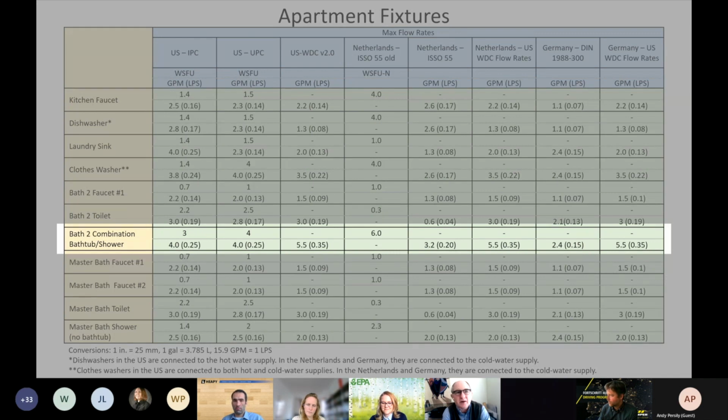So Dan, this is Gary. I've measured the flow rates coming out of combination tub shower valves, the ones that are ASSE 1016 protected for anti-scald, which is the modern tub shower valve in the US. And quite frankly, if you have 5.5 gallons per minute, I think the pressure drop through the valve is about 45 or 50 PSI.